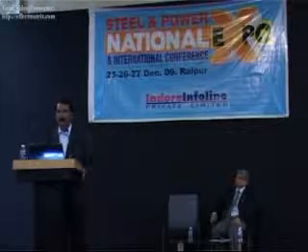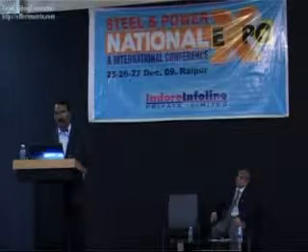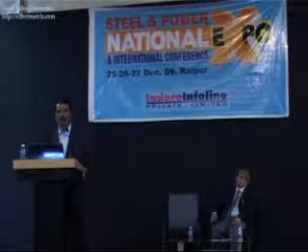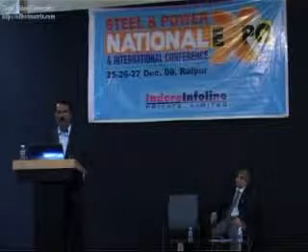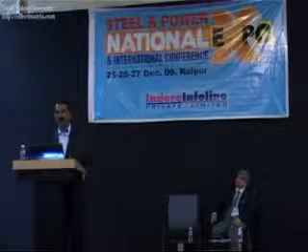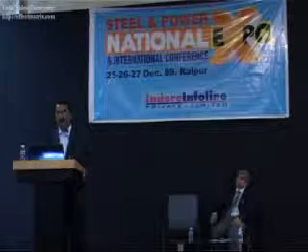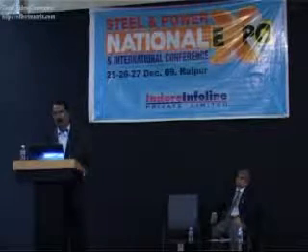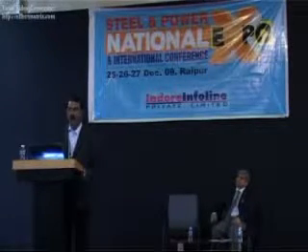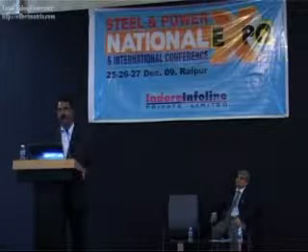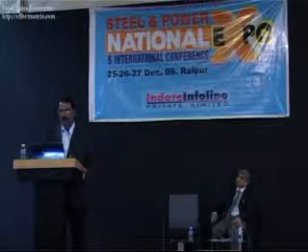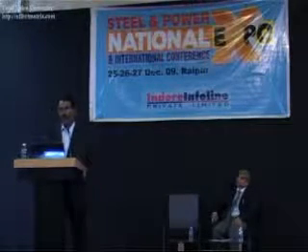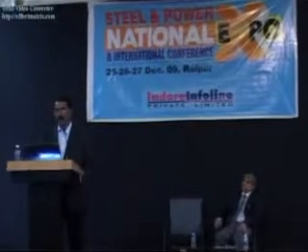As we have seen in the previous slides, in mold cooling circuit and machine cooling circuit, a high purity of water is used, which is often softened or DM water. By using that kind of water, we are able to avoid deposit problems which might be due to the dissolved solids present in the water. So we are finally left with the corrosion problem.